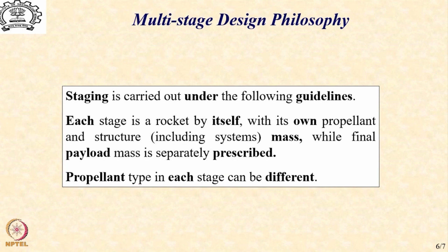And that also is one of the reasons why in most launch vehicles which are used for launching spacecraft for interplanetary missions, the last stage is typically the cryogenic, which has the highest ISP. Now you see the reason why the cryogenic stage is the last stage, because that is the most efficient stage. It is required to accelerate the smallest possible mass, so the largest amount of delta V we can generate by using even a smaller amount of propellant in the final stage.